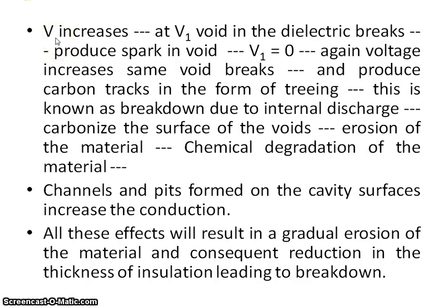Now if we summarize all this internal breakdown, what happens when we increase the voltage is that V1, the voltage in the void, reaches breakdown, the dielectric breaks and produces a spark, and V1 is equal to 0 again. Now the voltage increases, again the void breaks and produces a carbon track. In this way, as we increase the voltage, more and more sparks are produced in the gap.